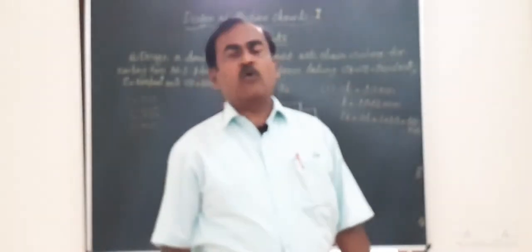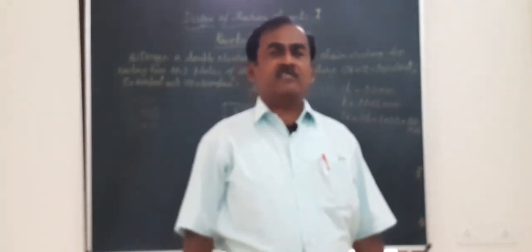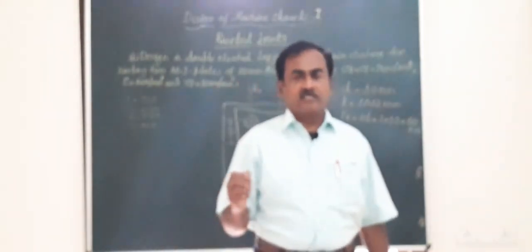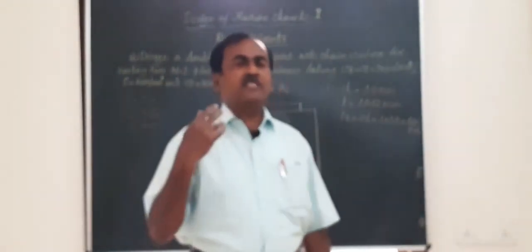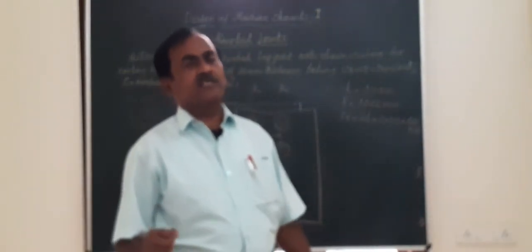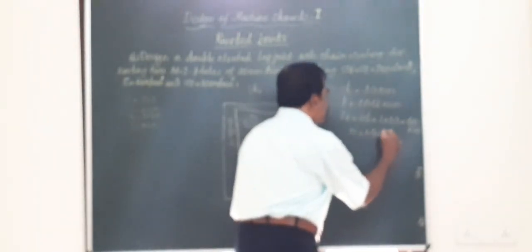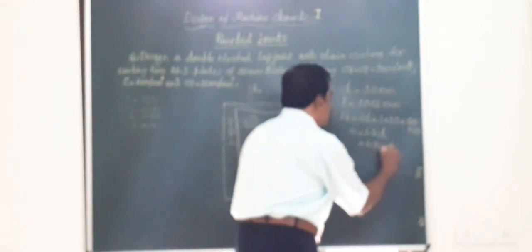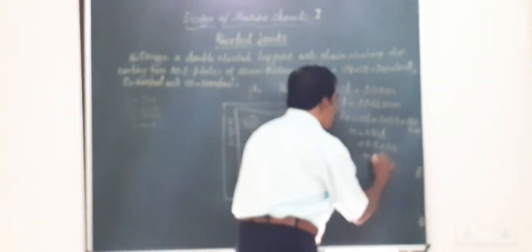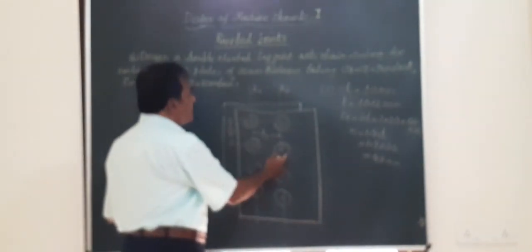So along with this, in the same step, we also calculate what is the margin to be provided. So friends, remember, for all the joints, lap joints or butt joints, whatever may be the arrangement of rivets, this margin is a universal value and is given to be equal to 1.5 times the diameter of the rivet. So 1.5 times the diameter of the rivet, which is 30, is going to be 45 mm. So we have got the calculations made for the longitudinal pitch, the transverse pitch, the margin. So we have got all the required parameters for designing the joint.